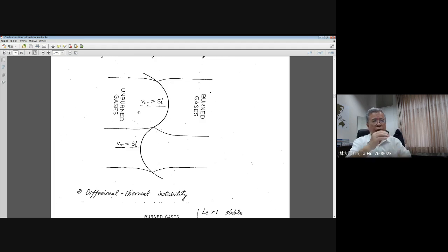But in this case, with a curved flame, this curvature effect gives some focusing that reduces the cross section of your flow tube or stream tube, so the upstream flow velocity increases. When you have an increased upstream velocity higher than the original flame speed, the flame will shift its position to avoid the part with lower approaching velocity.